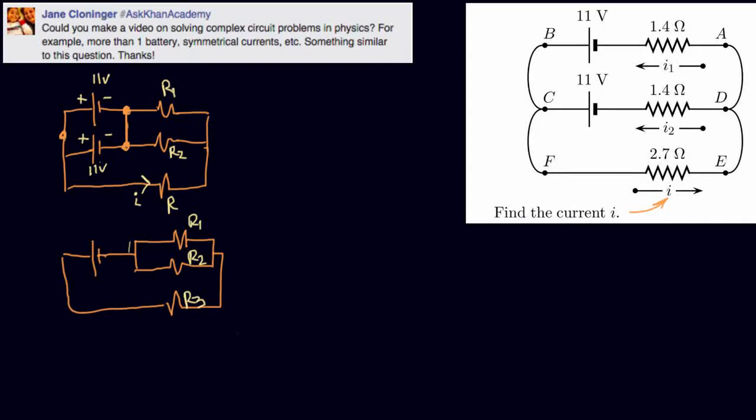Let's go to this color here. Okay, so parallel resistors, R1 in parallel with R2. I made up this symbol, two vertical lines. That means they're in parallel. And the formula for two parallel resistors is R1 times R2 over R1 plus R2. Now I'll plug in the values.